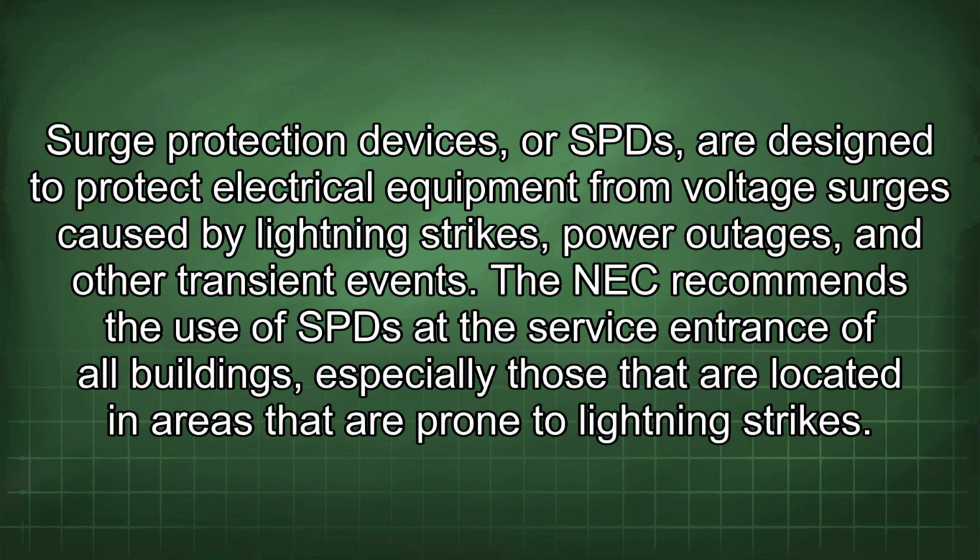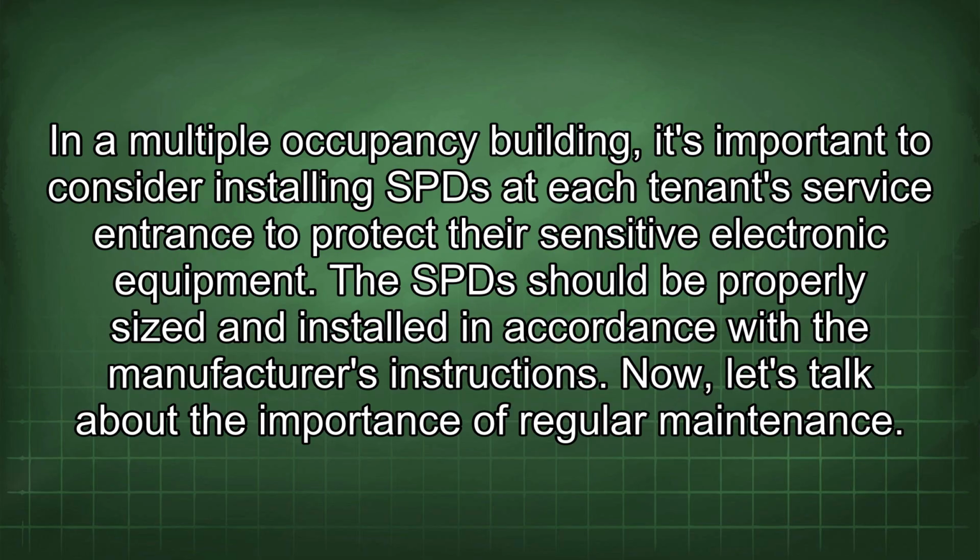Surge protection devices, or SPDs, are designed to protect electrical equipment from voltage surges caused by lightning strikes, power outages, and other transient events. The NEC recommends the use of SPDs at the service entrance of all buildings, especially those located in areas prone to lightning strikes. In a multiple occupancy building, it's important to consider installing SPDs at each tenant's service entrance to protect their sensitive electronic equipment. The SPD should be properly sized and installed in accordance with the manufacturer's instructions.